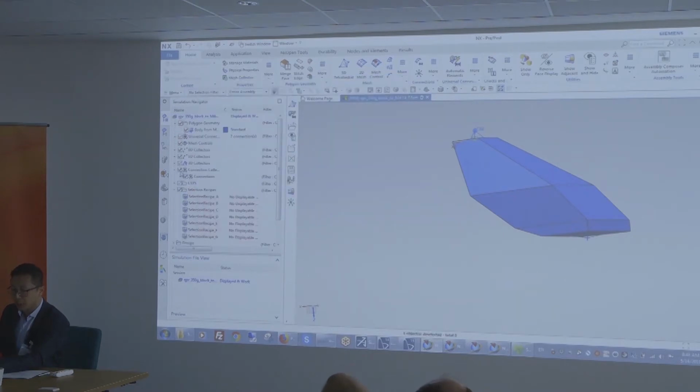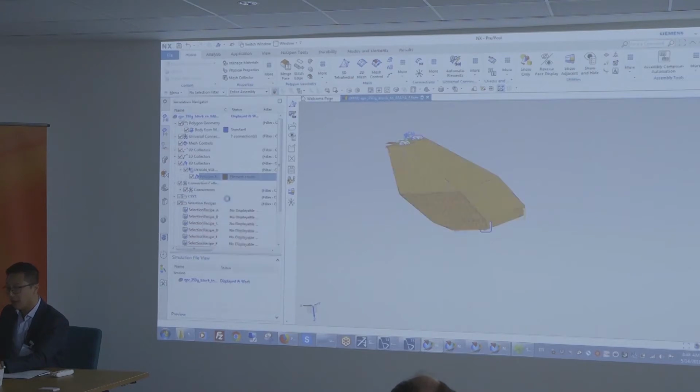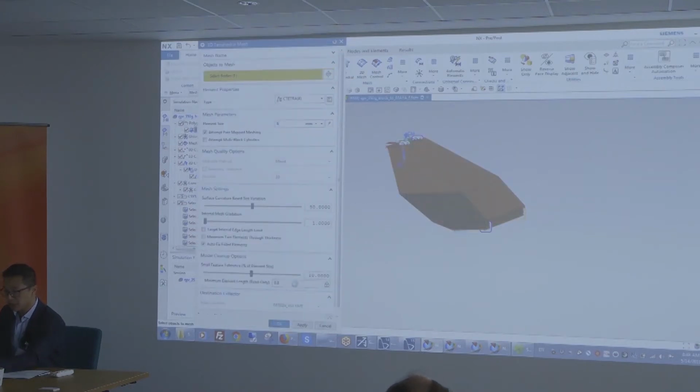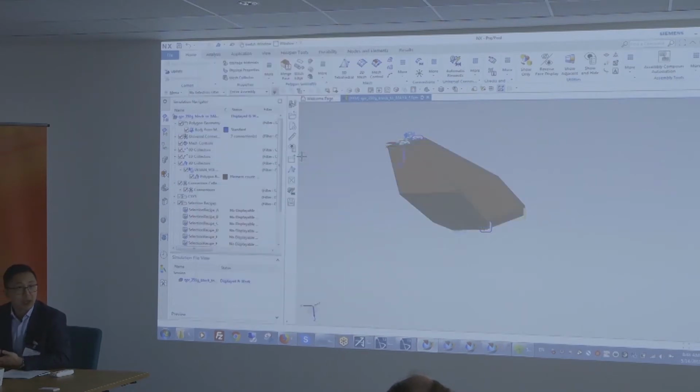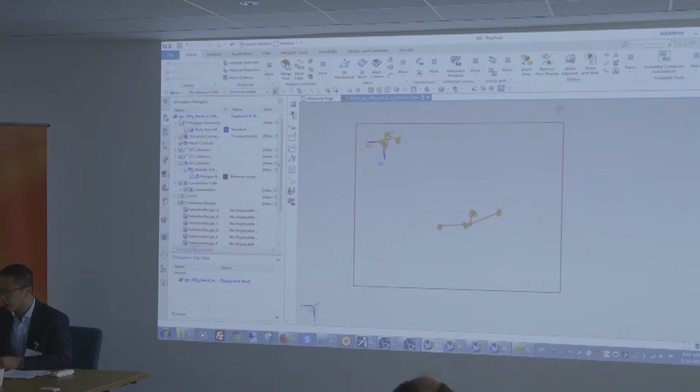And at this point, the connections are not created. What they show up as is just these functional requirements. So create a rigid connection in those areas. So I have a mesh, but I could very well go back in there and refine it, let's say 6 millimeters. And what I'd like is for my bolted connections to automatically update. And you see here there's an update requirement, and if I hide those and look at my 3D elements, it's been searching for all the elements that have been created around them.